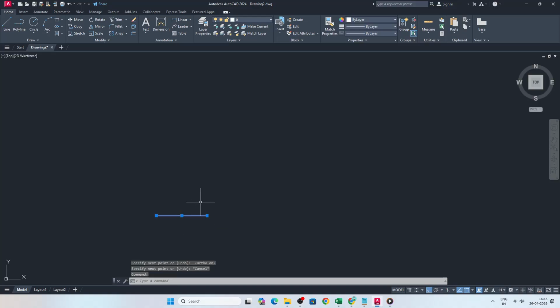Watch the command line feedback as you go. It will confirm each coordinate you've accepted. If you make a typo, press ESC to cancel the current prompt and re-enter the coordinate correctly. When you are done placing points, press enter to accept the final segment. If you need to cancel out of the command entirely instead, press ESC.